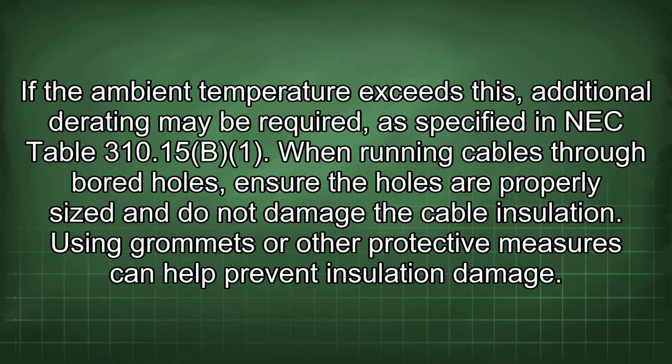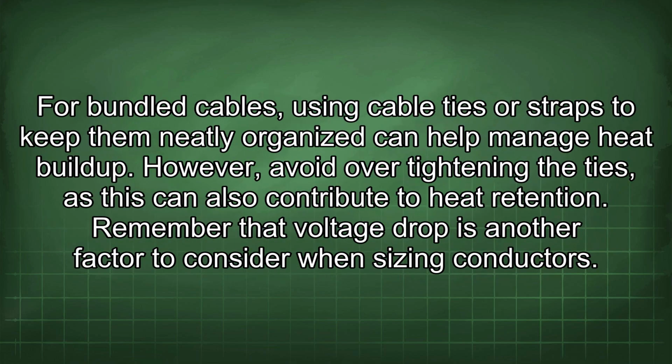When running cables through bored holes, ensure the holes are properly sized and do not damage the cable insulation. Using grommets or other protective measures can help prevent insulation damage. For bundled cables, using cable ties or straps to keep them neatly organized can help manage heat buildup. However, avoid over-tightening the ties, as this can also contribute to heat retention.